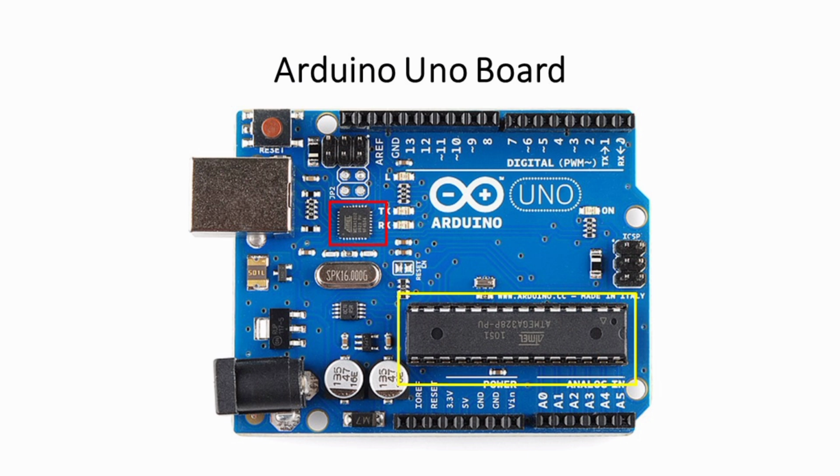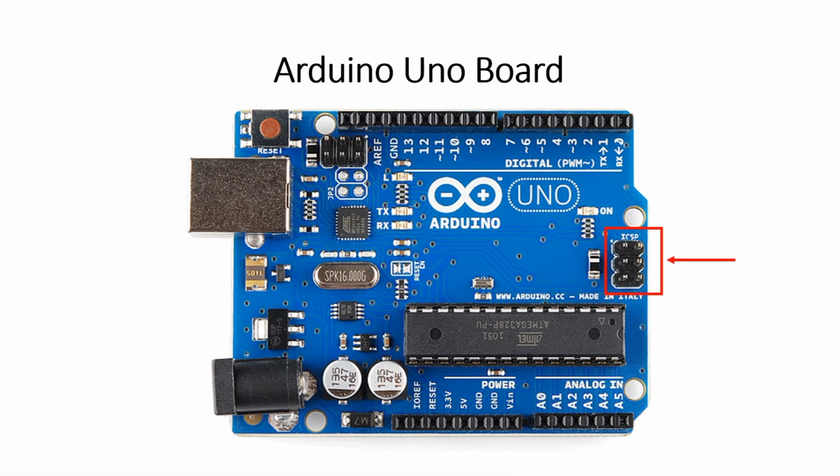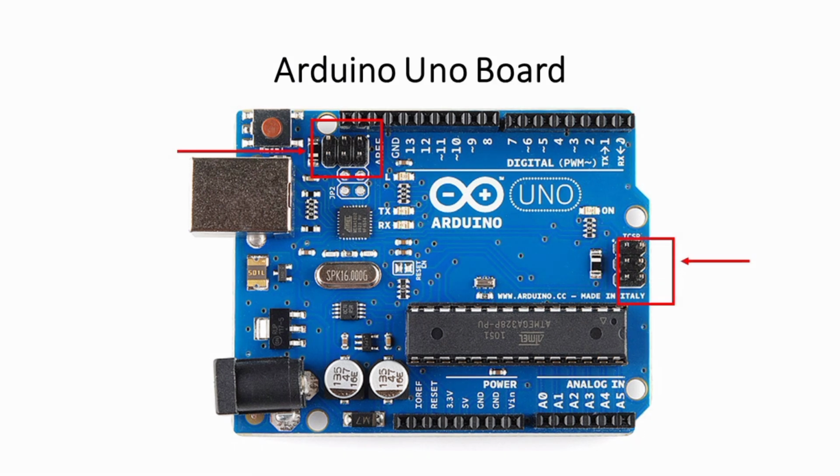USB is simply a protocol, and the Atmega 16U2 understands the USB protocol. Thus the data that comes in through the USB, the 16U2 translates into something that the 328 microcontroller understands. The same thing happens during the reverse process. When the 328 wants to send something, the 16U2 translates it into the USB protocol. These microcontrollers come with preloaded firmware, which allows the flash and EEPROM to be programmed. It also manages USB communications since the application program is loaded via USB.